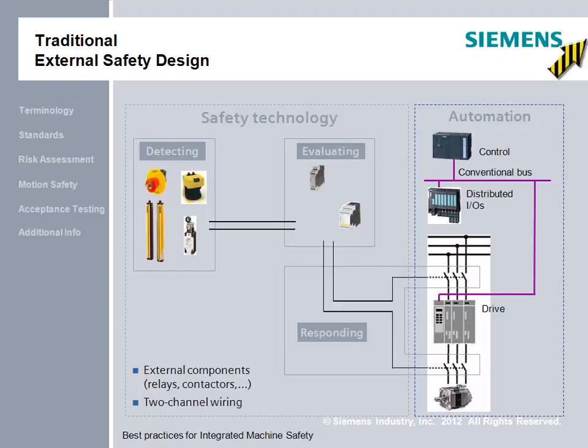It is typical that we need to use the conventional control system to stop, in this case, a servo motor, bring it to a stop before we open the contacts to the drive system. So even though this circuit works very well in some cases, it becomes limited very quickly when we look at the safety of the entire system.